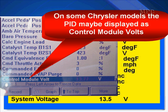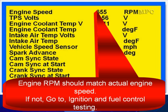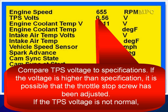Special note here, on some Chrysler modules, that system voltage PID may be displayed as control module volts on some of the newer models. Just like key on engine off, we're going to go down through the data and compare it to specifications. Engine RPM should match actual engine speed. If not, go to ignition and fuel control testing. Compare the TPS to specifications.